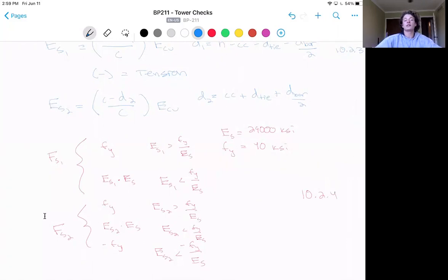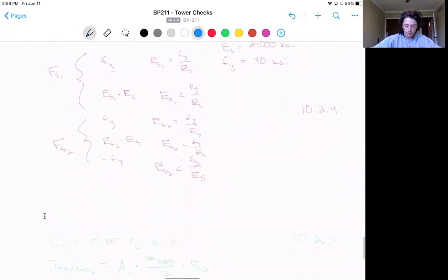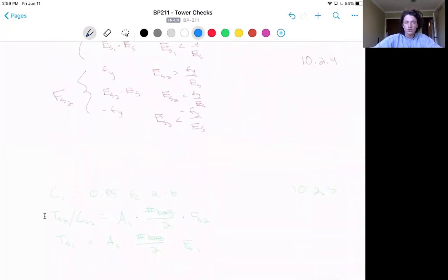Next, we'll calculate the forces in the concrete and steel pieces. So first, CC is the compression in the concrete. Remember that it is assumed no tension is picked up by the concrete. This is calculated by the equation 0.85 times FC, which is the compressive strength of concrete, times A times B, or the concrete compressive strength multiplied by the dimensions of the concrete compression block. Remember that another 0.85 is multiplied into the equation to account for the concrete displaced by steel in compression. This comes from design assumption number 6, section 10.2.7.